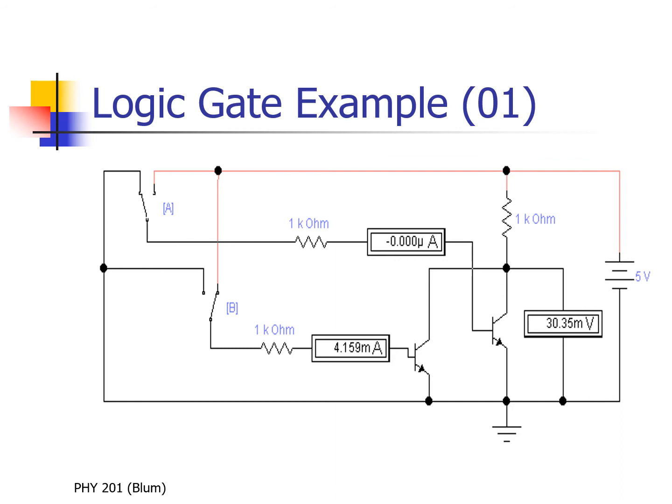And so we see in the collector emitter part of the circuit, we have the 5 volts. It goes through the 1 kilo ohm, and then it goes through these two transistors in parallel. They have now the effect of a low resistance, and so most of the voltage is dropped across the 1 kilo ohm resistor, and only a little bit of voltage is left to be dropped across the transistors. And so we've put in a low and a high, low for A, high for B, and our output across the parallel transistors, which we're considering the output of the circuit, is now low. It's in the millivolt range.